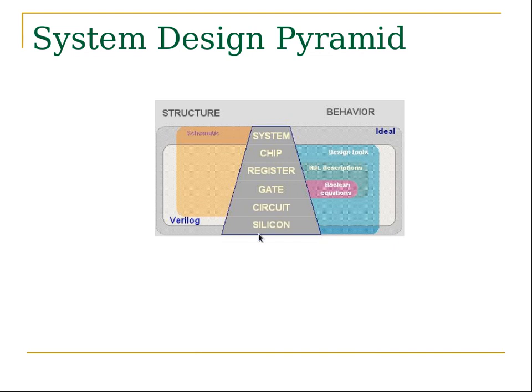Good, the system design pyramid. Hopefully some of this makes sense. The silicon's on the bottom. Then you have your circuit, where your transistors and gates are. Next come your registers, how you build them, put them on there and connect them. Then your chip will be a combination of all these gates and registers put together, and eventually become a system. What Verilog is going to do is let you specify on the circuit level, gate level, or register level, which will be your behavior, data flow, or structural mode.